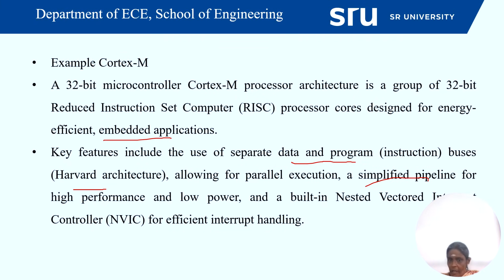And it does have the built-in NVIC. So NVIC means nested vectored interrupt controller. Why do we use NVIC? So there are special applications for NVIC. If we use it, it causes efficient event handling. That means interrupts are handled efficiently, and it directs the CPU controller to the correct interrupt routine.